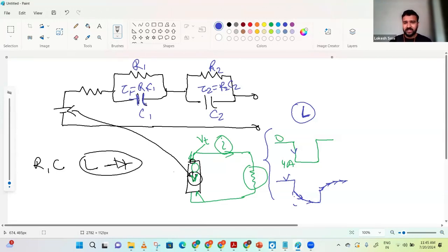Someone was asking how to know these RC values. There are multiple tests. One of the popular tests is the HPPC test, where you take a cell, put it under test, and do pulse discharge in the cell, from full charge to full discharge. And then you see a behavior of voltage like this. It would just keep falling like this with these pulses. From this data, as you know, this is RC behavior, you would derive all these R1, C1, R2, C2, and RS values.